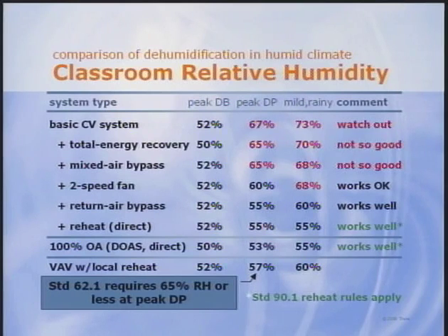And finally, most VAV systems deliver dry primary air at all conditions, so they maintain reasonable zone humidity without humidistatic controls. We covered analysis of these and other dehumidifying systems in detail in an earlier broadcast and in an applications manual. In summary, to comply with standard 62.1 requirements for dehumidification, pick the right system and control it right.